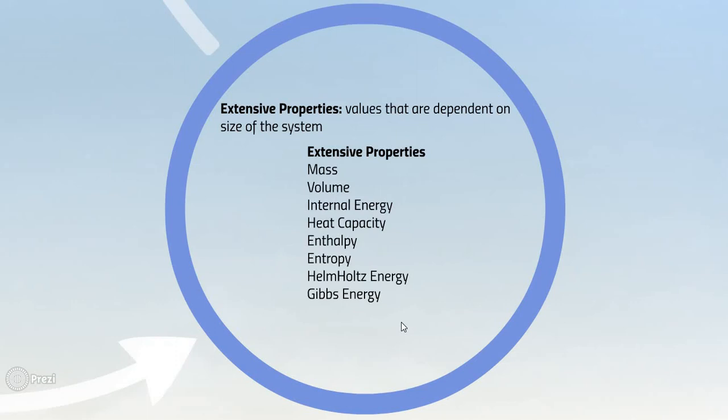Extensive properties. The properties of the system whose value for the entire system is equal to the sum of their values for individual parts of the system are called extensive properties. For example, total volume, total mass, total energy, or all types of energy are included in extensive properties, except specific properties. Where the word specific appears, it will denote intensive properties.